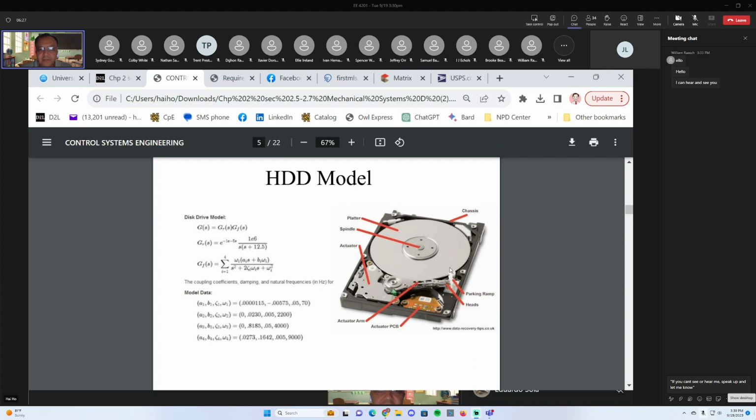We looked at this drive, and very similarly, its transfer function is a cascade of the motor, right? And there's a computational relay, and these are resonances. So if you combine all these together in terms of product, then you get a high order transfer function that represents the actuator system here, the servo system.